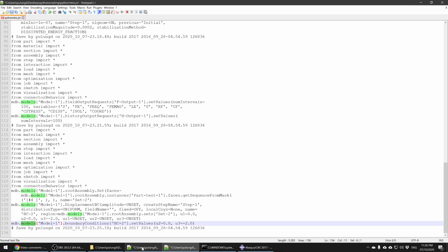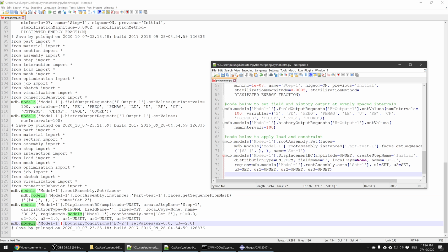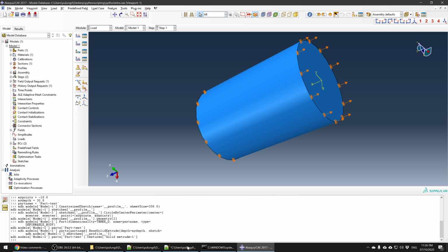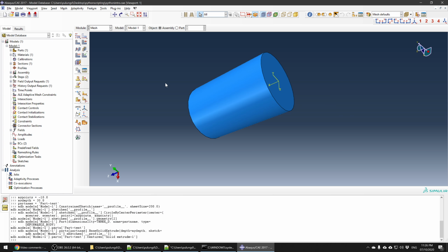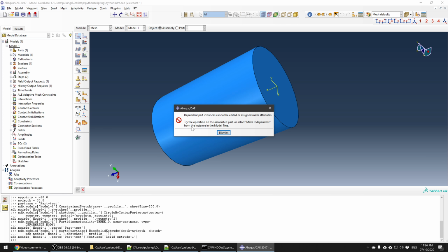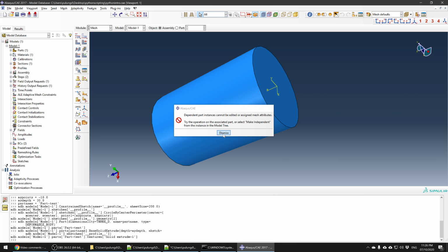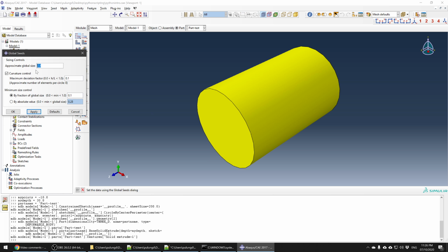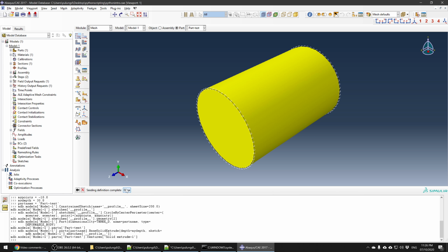Okay, and this is the okay. So I make the load and then the mesh. Now the mesh, the only thing you need to do is first you create set instance. Oh, it should be in the part instance. So you go to the part, you go here, set part, and then you put number. For example, in this case 1.0. Click done, and then you click mesh part.